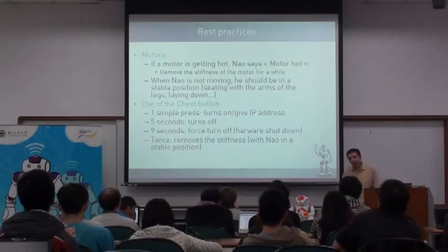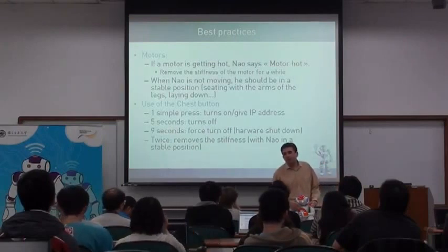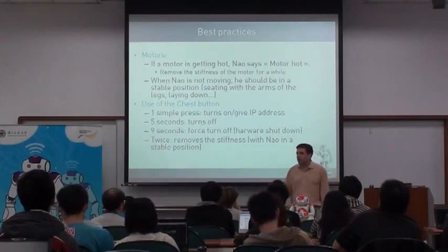And you can also use the chest button to switch off the robot, of course. If you press for 5 seconds, it will make a normal shutdown. If you press for 9 seconds, it's a hardware shutdown.